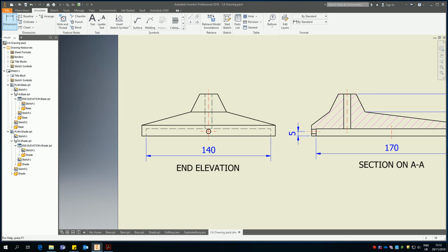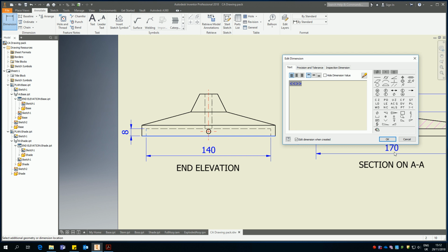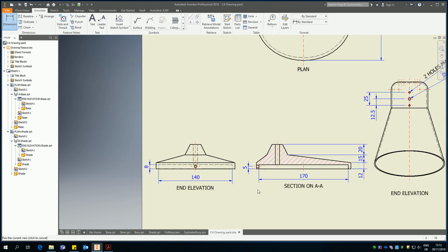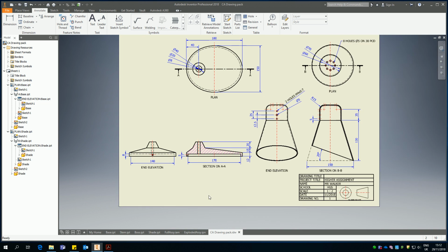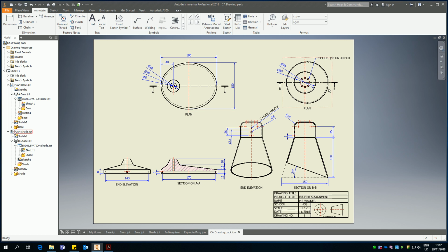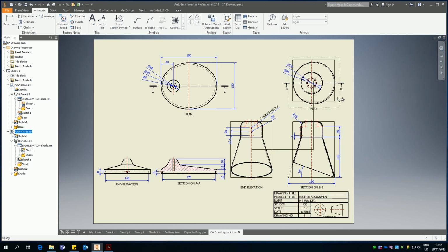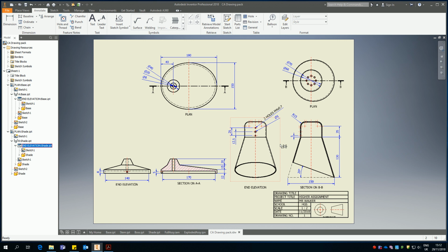So be careful with this. Sometimes if you maybe selected that and that, oh no, I wouldn't. Just make sure that you are getting a gap in between your dimensions. You want your projection lines to actually lead off the shape and not be too close. Okay, so I'm maybe going to delete this, and this will give me a bit more space to move this in to the right and allow me to lay this out in a neater way.